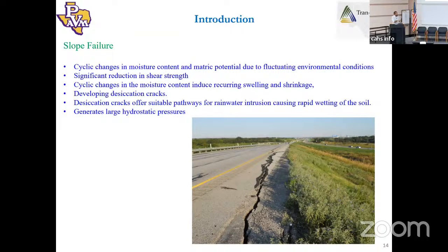Now, the soil is actually taking its own load, right? The soil has its self-weight, and also whatever traffic or vehicles are passing through the lanes, the slope is carrying those loads. Now, if there is an easy path for water, the water will generate hydrostatic pressure, and the soil will have to carry that hydrostatic pressure as well. But maybe during the design, we didn't consider that hydrostatic pressure. So those cracks will add additional implied stress into that soil layer.